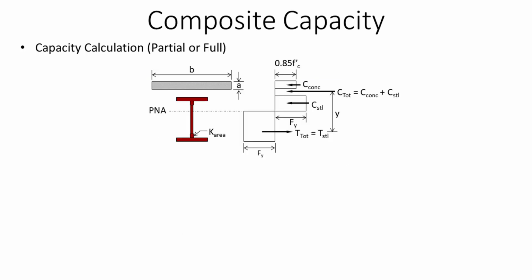In visual analysis, the member's pre-composite state is defined in the Modify tab of the project manager in the design view. For the composite condition, visual analysis automatically calculates the capacity for the full composite or the partial composite beam based on the strength and the number of studs engaged at a specific location along the member. Therefore, you can design with any level of composite action in the program.